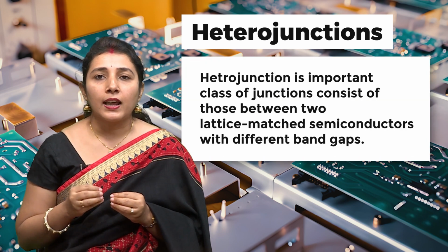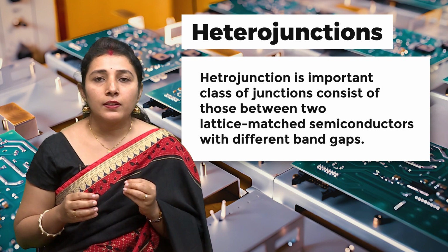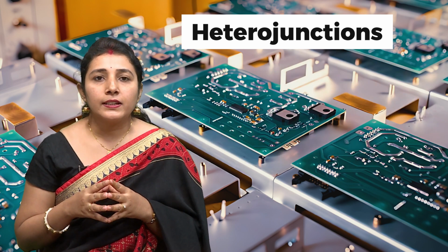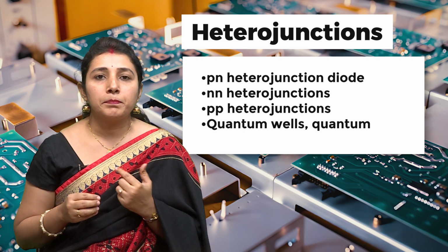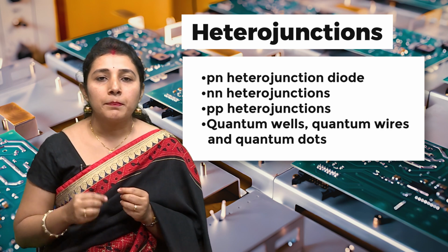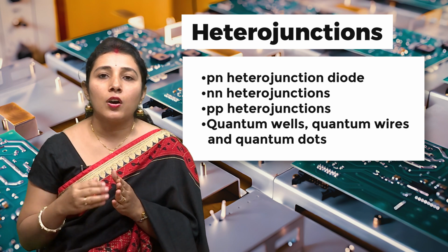Heterojunction is an important class of junction consisting of those between two lattice mismatched semiconductors with different band gaps. Let's consider four commonly encountered kinds of heterojunctions: the PN heterojunction diode, NN heterojunction diode, PP heterojunction diode, and quantum wells. We also call them quantum wires or quantum dots.